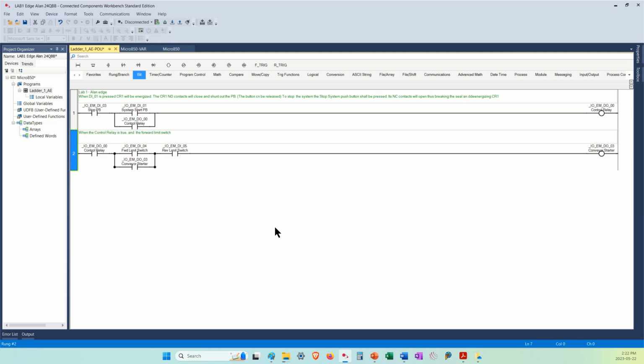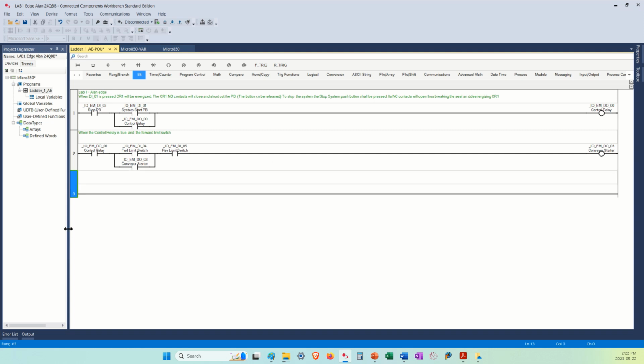So part 2, we're going to add one more rung. We'll start with our new rung here. Drag and drop. Excellent. And what they want to do is put a pilot light that says the machine has stopped. So I'm going to grab my pilot light first, and it's going to send it way over off to the right. So now I can insert a contact ahead of it.